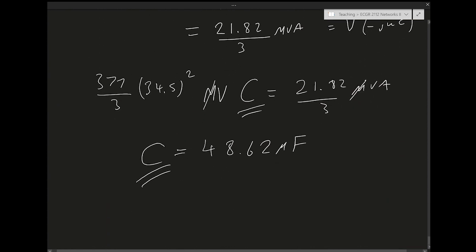All right. So with this example, we conclude our discussion of polyphase circuits, balanced polyphase circuits. For unbalanced polyphase circuits, things get more complicated. You will have to go back and do mesh and nodal analysis on the different phases. All the assumptions that we had for balanced circuits don't follow anymore, right? That's why balanced circuits are a very important special case, and we always try to maintain balance when we implement three-phase systems.